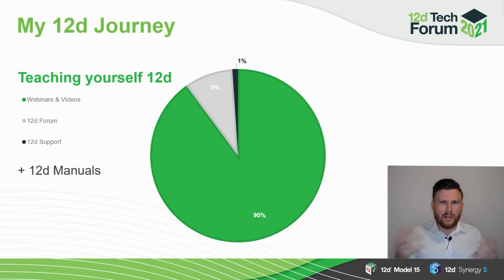It wasn't until about 3 months in that I realized you could use the middle mouse button or the scroll wheel to select things. Just taking that one step out made life so much easier, so much faster. There are lots of little tips and tricks like that in the 12D manual, on snapping or drafting things, that can really help you use 12D efficiently. Or that's what I've found at least.